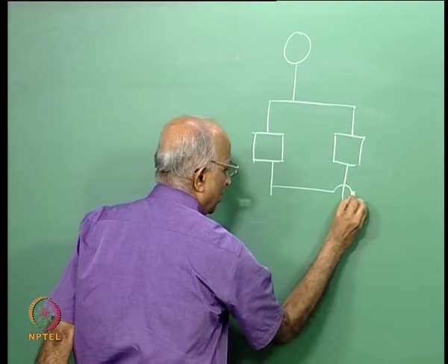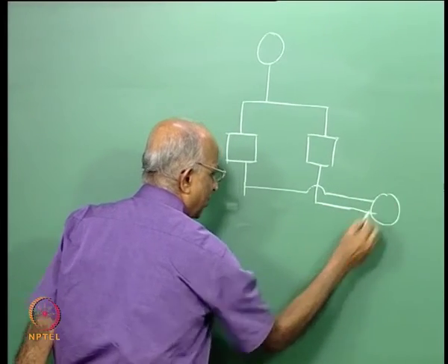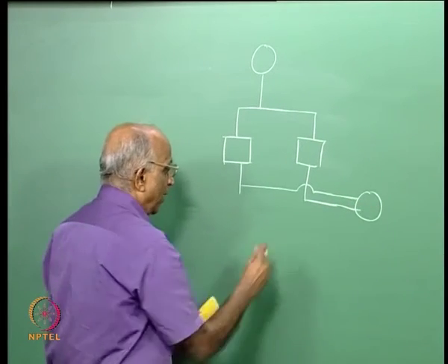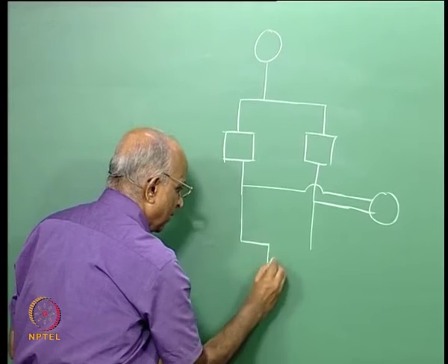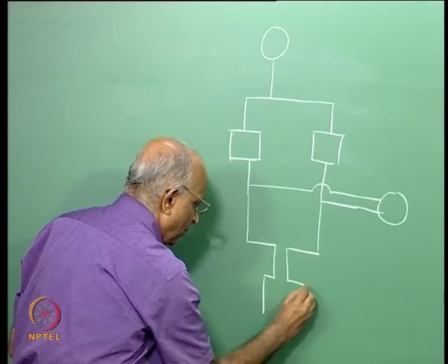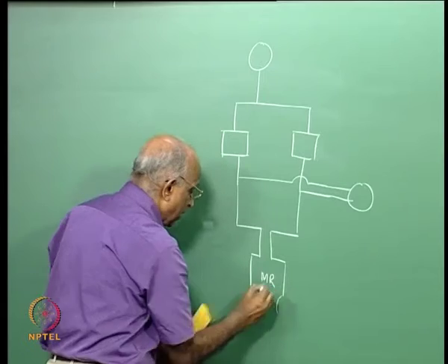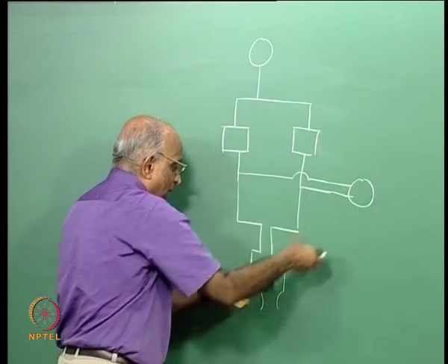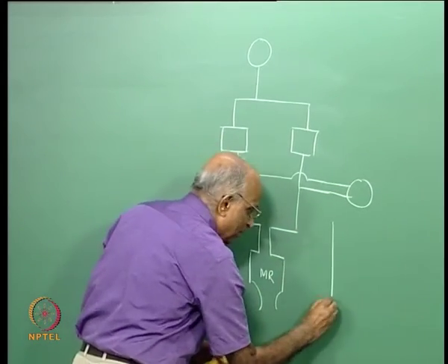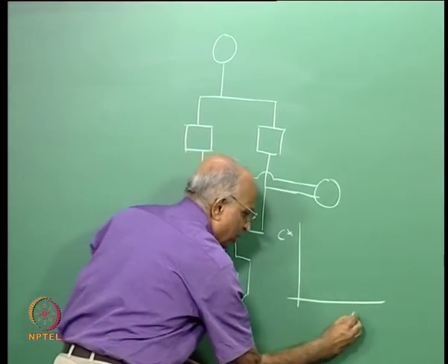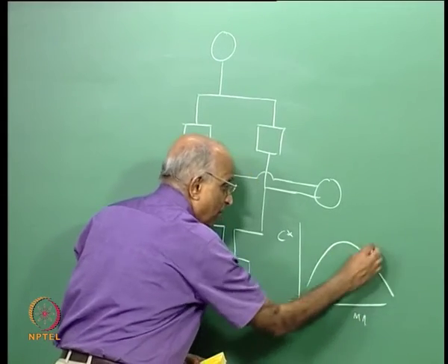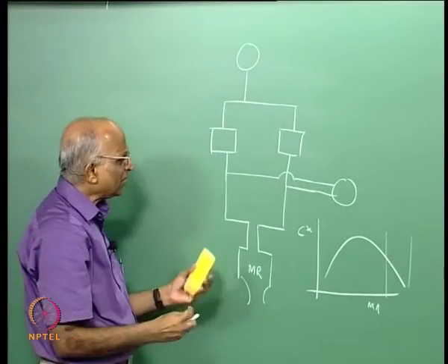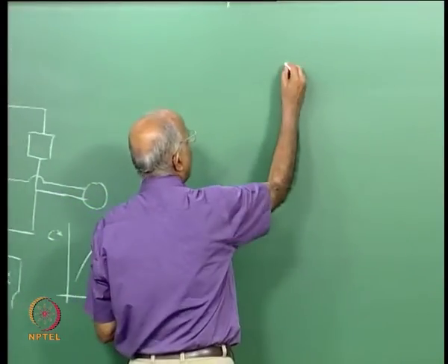We took a little bit of the oxidizer, a little bit of the fuel into the gas generator, and this is, mind you, very fuel rich, and therefore I am bleeding more and more of it. And what happens when I bleed more and more of this? The mixture ratio of the engine keeps increasing because I am drawing a lot of fuel into this, more of the fuel rich propellants. Therefore, this becomes oxidizer rich, and again, what is the dependence of C star or Isp with respect to mixture ratio? It is an optimum, it comes down, we start operating the engine in these conditions, and that is why the performance begins to fall. Therefore, let us quickly derive an expression for a gas generator cycle.